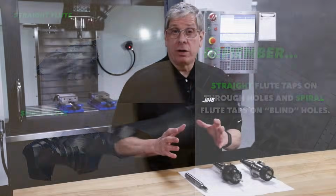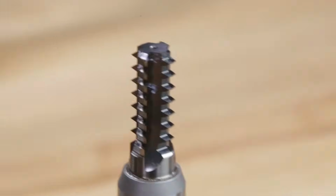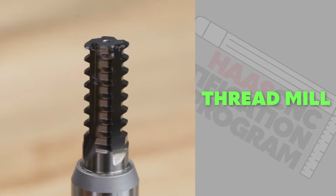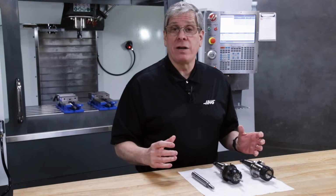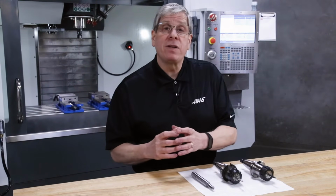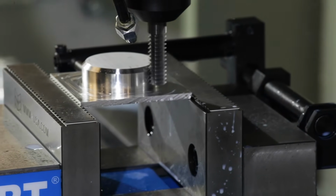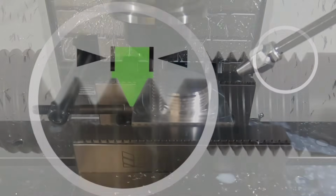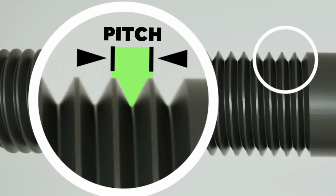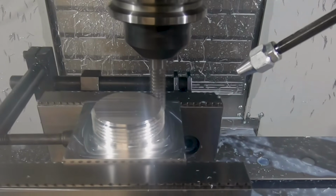Now, a thread mill cutter can be a single point thread mill, or it can have multiple thread forms on it, like this one. Typically, thread mills like these are used to cut screw threads on the outside of a workpiece or on the inside diameter of a larger hole. With thread mills, we program a circular motion with a helical move that is equal to the pitch of the thread. The pitch of the thread is the distance between each thread form. It's also the distance a screw travels in one full rotation.